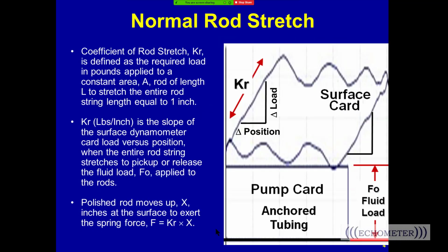So this is a fairly simplistic surface dynamometer card. Here's our surface dynamometer card, and here's our pump card. And I show a plot here that says this is the load going up, the position horizontal. It's a change in position horizontally, change in load vertically.